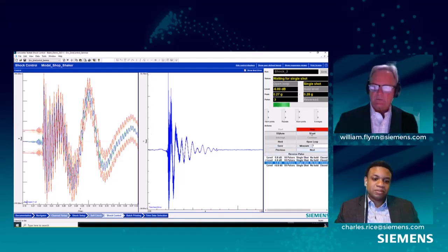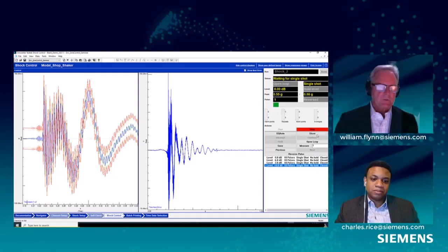If I go to the next one, I'll shoot. It's a bit closer. It's got a good estimation of the transfer function, and shoot again. And it's even closer after an updated transfer function. Let's go to our final level, full level, shoot. You can see its nonlinear response, very minor, but we go again, and now we'll update the transfer function with the next one, and we should be closer to the reference, which we are.